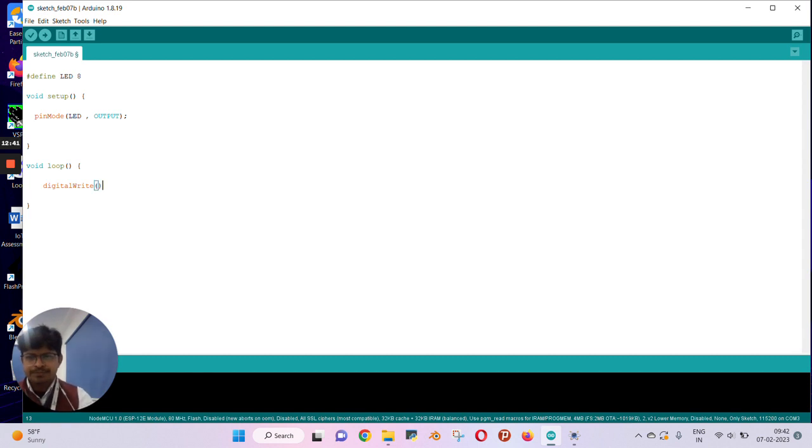In the bracket, we write the pin we want to turn on or off. If we want on, we write HIGH, and if we want off, we write LOW. Here we want to glow the LED, so we write HIGH.